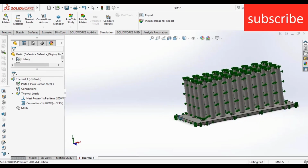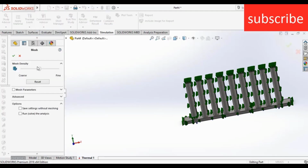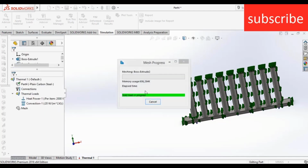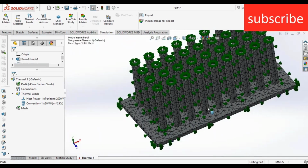Our setup is ready, and what you can do is right click on mesh and create mesh. You can increase or decrease the quality of mesh as per your requirement, or you can set parameters as per your requirement, but here I don't need it because my main aim is just to show how to do meshing. So after clicking OK, here you see the mesh. Remember, the higher the quality of mesh, the higher the quality of the simulation result. After that, click on run this study.